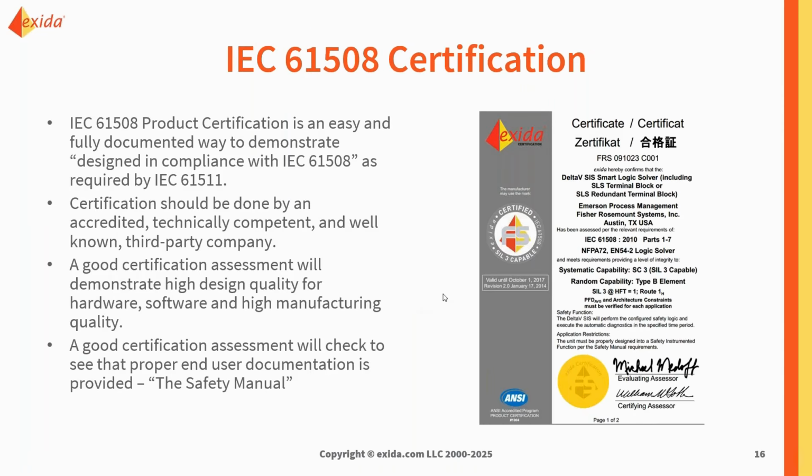And I always tell the designers the easiest method is to use 1508 certified devices, because it's an easy way to document and demonstrate compliance with 1508 as required by 1511. It should be done by an accredited, technically competent and well-known third-party company, although manufacturers can self-certify if they choose. A good certification assessment will demonstrate that there's high design quality for the hardware, the software, and the manufacturing. It will also check to make sure that the proper end user documentation is provided. In other words, the safety manual.